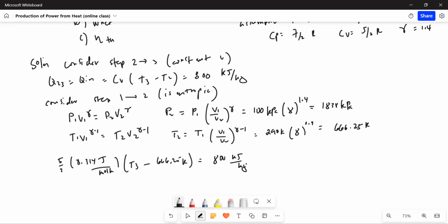Okay. So, we want to convert this term into molar. So how do we do that? Use your dimensional analysis skills. 1 kilojoule is 1,000 joules times 1 kilogram is 1,000 grams, so times the molar mass of air, let's assume that it's 29 grams per mole.